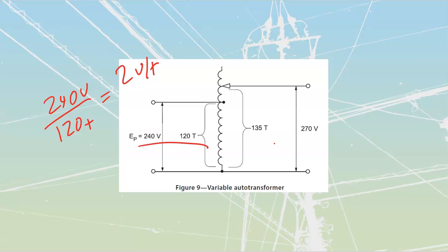Now, the way that they're doing this calculation is backwards because they're starting to talk from the main primary side. They're saying, this is what we want to have out of here. What am I going to apply? Now, it's not the way where these things are going to happen. What we're going to do is apply a value of voltage, and we will adjust the turns on the output. We don't ask Hydro for what we want. We got to adjust to what Hydro is willing to give to us.